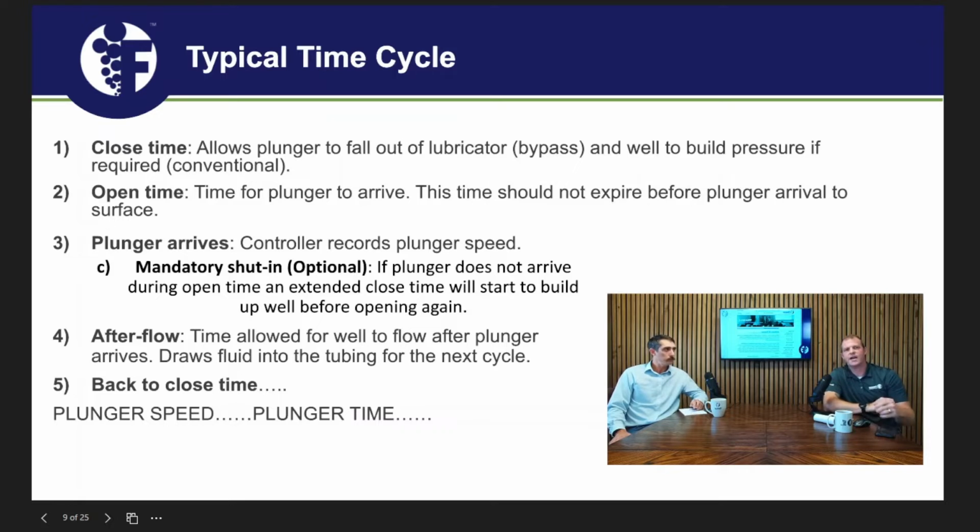Okay, that makes sense. And of course, in our Plunger Lift 102 course, we'll talk a lot more about it. But each one of these features is, one, adjustable, so the operator or the plunger technician can make changes. And two, you can use this data to track how well your system's optimized. With an operator SCADA system, we probably want SCADA on these things, so we can record and see that data, and they can use that data to understand how well the system's running. Perfect.